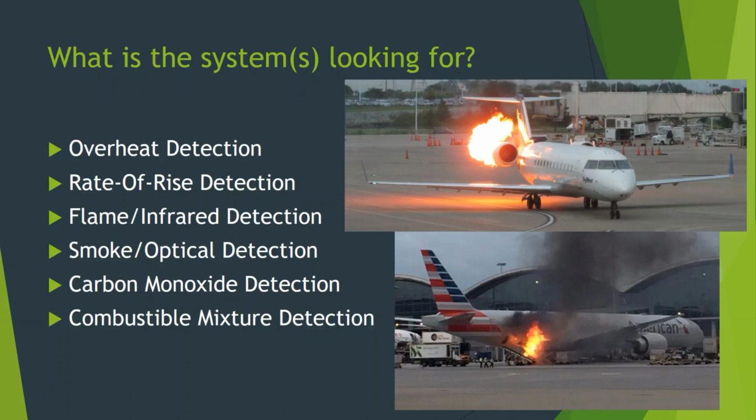Carbon monoxide detection, not as common in large aircraft, right? All your small aircraft are going to have that, particularly if they have an exhaust muffler type heat system on them. But there's really not a lot of sources of carbon monoxide on transport aircraft, but it's possible.